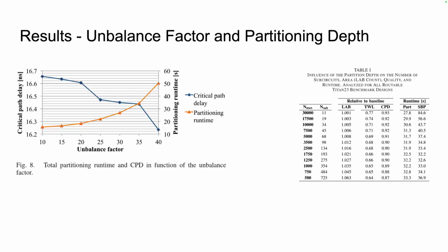Okay, and I guess they will lose some information if they pass a lot of stuff, which they're probably not doing. If you had lots of overlapping clocks and so on, then you have to pass more information to reconstruct that on the other circuit. But it's also relatively rare to have lots of overlapping clocks, like clocks whose timing paths overlap. Usually your timing paths are within a clock domain with a few in between.